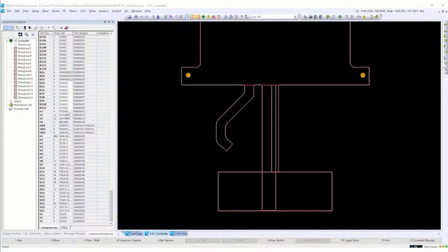Your conductor spacing on a Flex is actually better than a rigid Flex. You can get down to 2 mil, even though I guess you can do that on rigid boards as well. Vias are very small, again, because everything is laser cut with polyimide. So the aspect ratios that you can use on vias are down to 12:1, unlike rigid boards, where it's typically around 8:1.